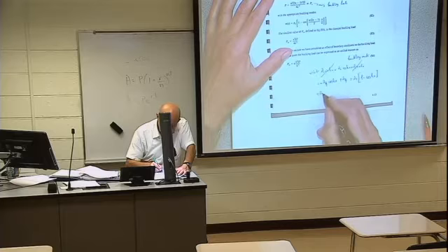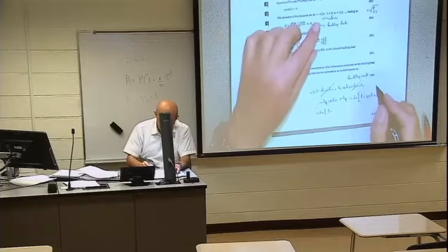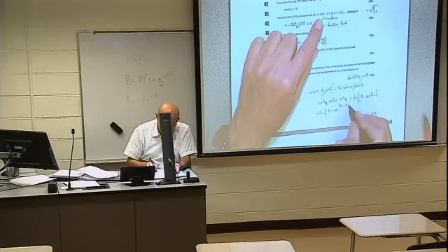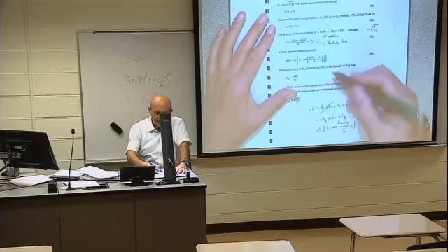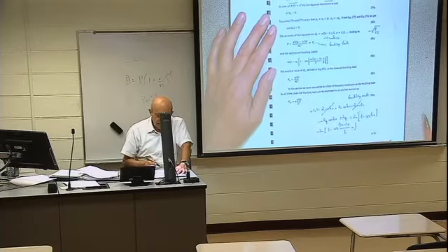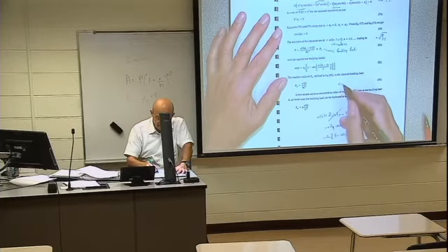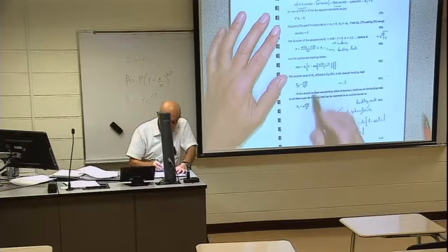Or that equals a4 times (1 minus cosine of (2n minus 1) pi over L times x), where I substituted k from here. So that is what is written here, and that is a mode shape. The smallest value is n equals 1. For n equals 1, we get the buckling load, P classical or P critical, we used P critical, equals pi squared EI over 4L squared.